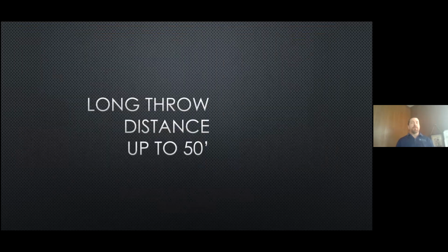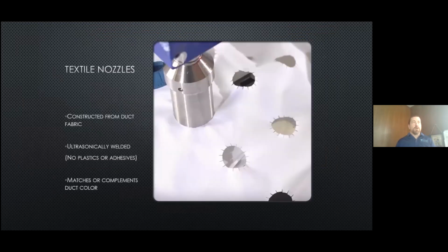When we move into applications like a lot of indoor manufacturing, there will be these longer throw distances, starting to move out 50 feet or so. We're going to move to nozzles. And the way Prihoda does nozzles is a little bit different than everybody else.